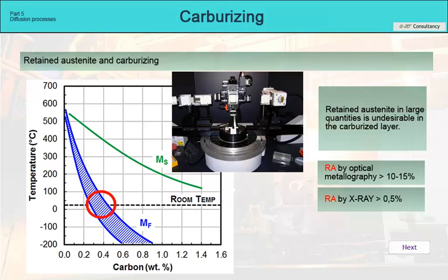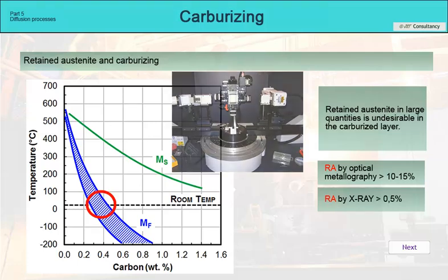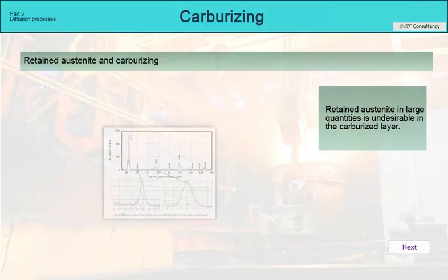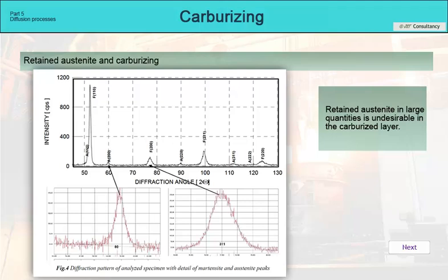In some cases, the method of magnetic induction or Mossbauer spectroscopy can be used, distinguishing between magnetic and paramagnetic components in steel. In both cases, the detectability of residual austenite is from 0.5%. The figure shows an example of an X-ray diffraction record for a residual austenite content of 9.6 plus minus 1%.